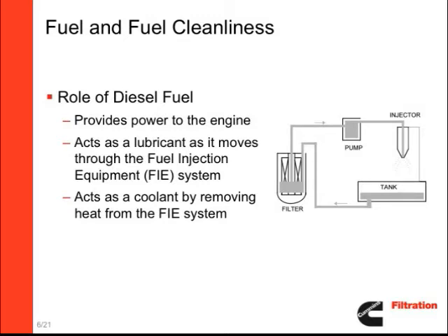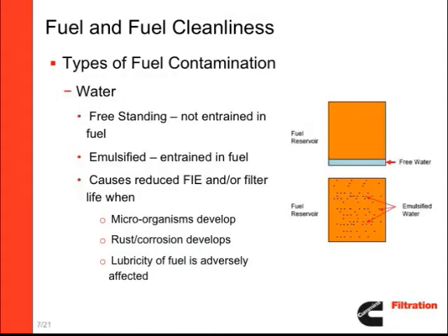Diesel fuel has 3 main roles in the system. First, it provides power to the engine. Second, it acts as a lubricant as it moves through the FIE system. Finally, it acts as a coolant by removing heat from the FIE system. The importance of clean fuel in HPCR systems can't be overstated.